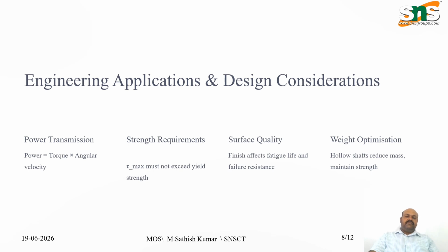Power transmission: P equals torque times angular velocity. Strength requirements: maximum shear stress must not exceed yield strength. Surface quality: finish affects fatigue life and failure resistance. Weight optimization of the shaft reduces mass and maintains strength.